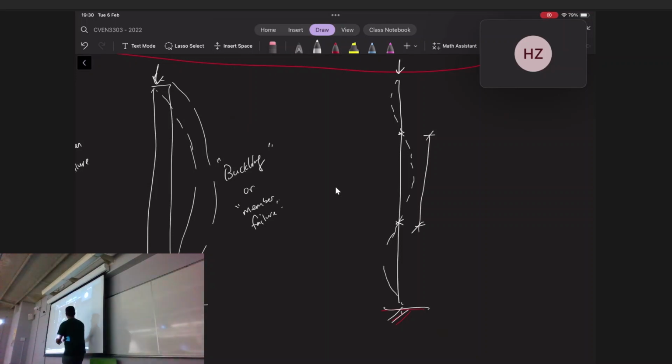Those are the points where you take your length. That's a point of contraflexure, that's a point of contraflexure, and that becomes the buckling length. Over here, there are only 2 points of contraflexure, top and bottom. So the deflected shape matters a lot because it gives us the length over which it is buckling. It may not be very obvious, but here it is. Let's talk about a real life building then.